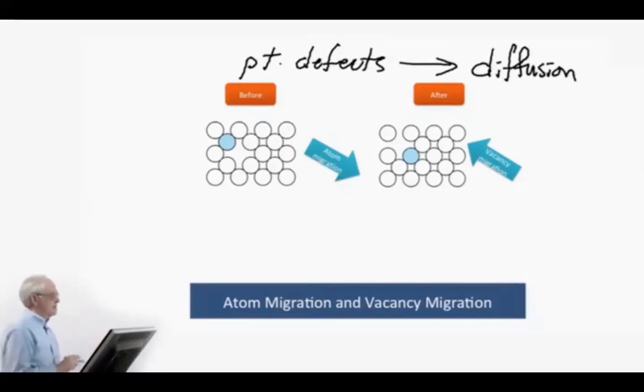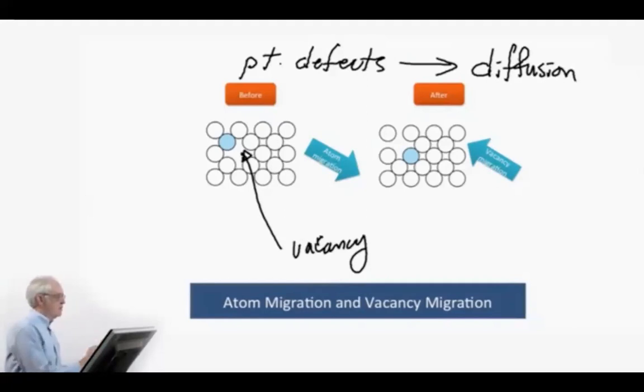And specifically, those individual vacancies, as illustrated here, and we can just give ourselves a quick review of the concepts from crystallography. What we see here is that familiar face-centered cubic pattern that we saw in the unit cell of aluminum back in that discussion of crystallography, and that face of the unit cell would be a 100 plane. Again, that front face of the unit cell. And so if one of those atoms is missing, one of these vacancies that's been produced by thermal agitation, thermal activation, by bringing the material to increasingly high temperatures, now that provides a place for one of the adjacent atoms to move into and thereby provide atomic migration.